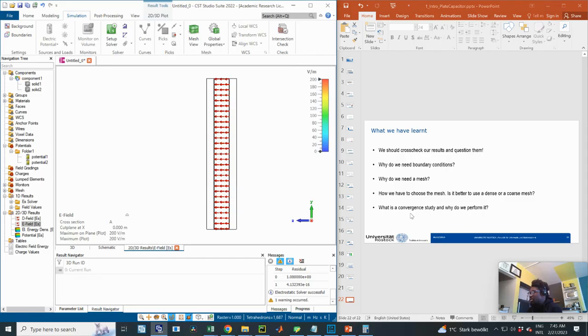We are okay with an error of maybe 1e-8, right? And we won't know what the error is if we just solve one problem with one parameter, and don't refine the mesh and see how the solution changes with it. So that's why we do the convergence study.